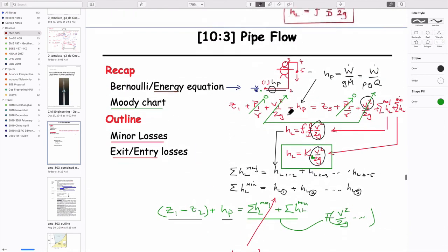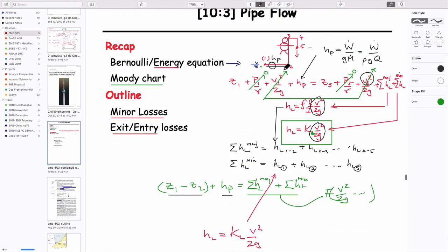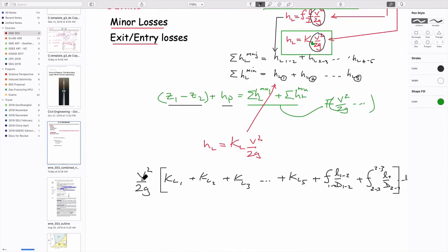So if, for example, the cross-sections of the fittings and the pipe were the same all the way through, then you can take a single value of velocity out, because v1 a1 equals v2 a2, etc. And so you ease it, and all you need to know is what these loss coefficients are.